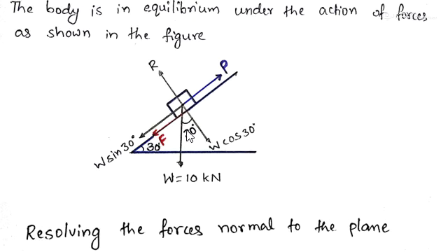So if it is 30 degrees, here also this is 30 degrees, and this component of W is nothing but W cos 30 degrees, and the component parallel to this inclined surface is nothing but the sine component, that is W sine alpha, or that is W sine 30 degrees.